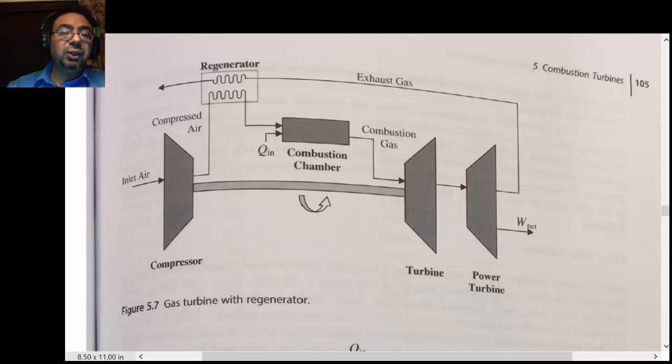And this should remind you of the Rankine cycle from Thermo 1, which you probably had in the last chapter of Thermo 1. They had a regeneration modification to the cycle, where they take a little bit of the hot steam from the turbine and heat the water before it goes to the boiler, right?